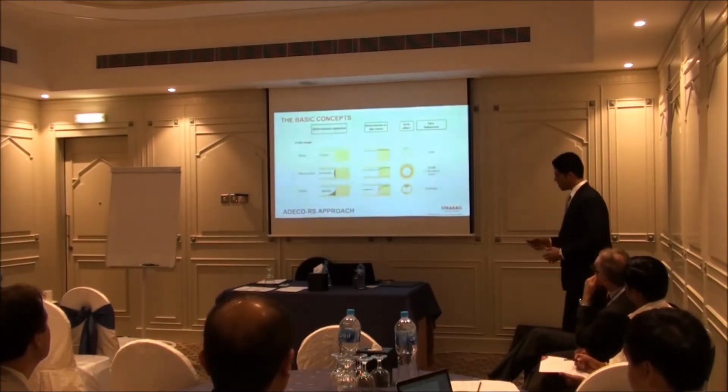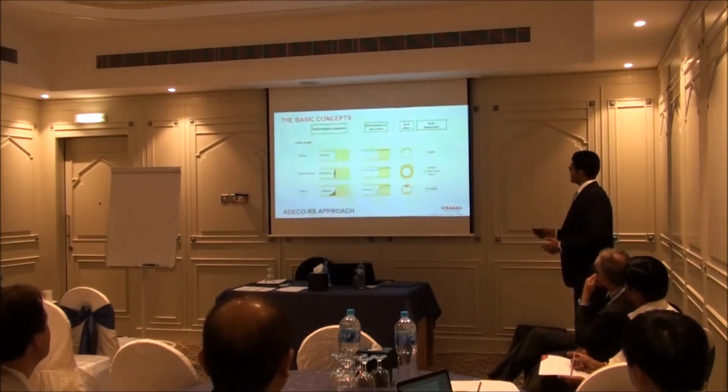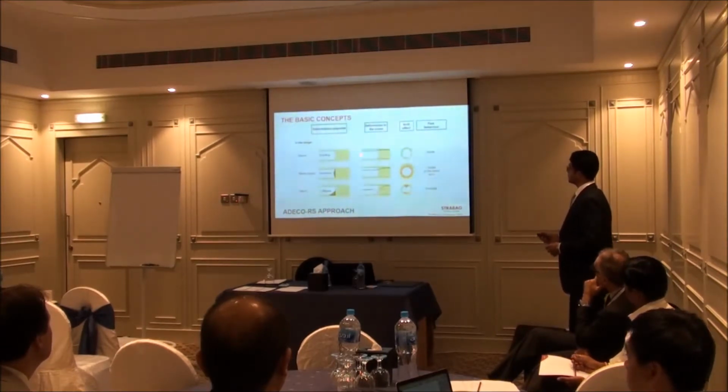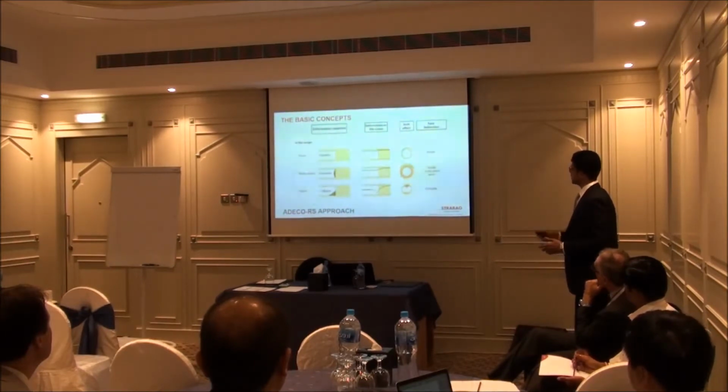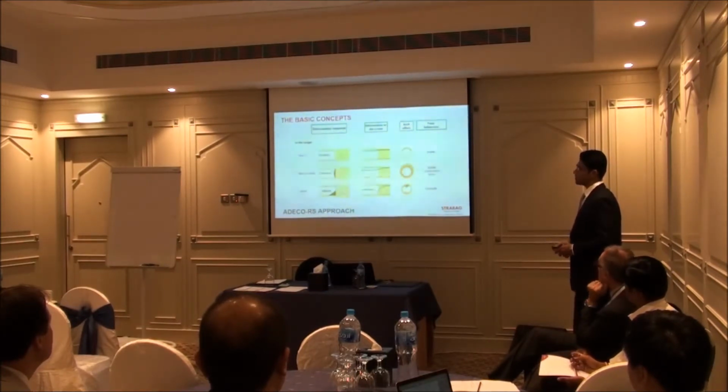The same concept, now elaborated further. We can have one of three possible stability situations. One is where the arch is formed right next to the cavity, and it is a stable condition, and the arch effect is formed within the elastic range with the least deformations. The second situation can be where an arch is not formed exactly around the cavity, but at some distance, in the elastoplastic range, and there will be some deformations, and the stability will be only short term. So some interventions are required.